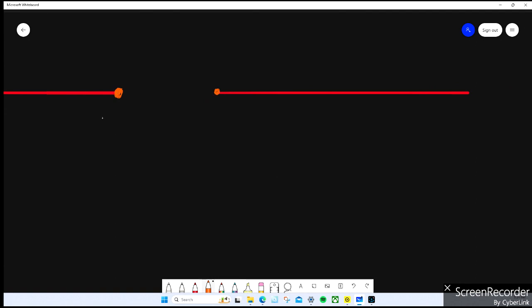It's a normally open push button. Okay, I'll freehand this. Again, let me back this up. If I were to do this, this is not a normally open push button. Even though there's space in here, even though it's an open circuit, this is not a normally open. This would be considered a normally closed held open. So make sure when you're doing a normally open push button, you're actually showing it as you should.